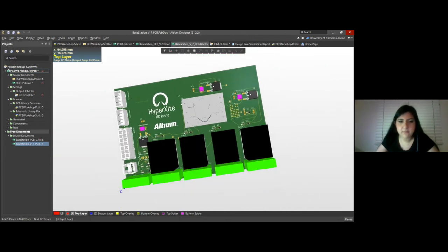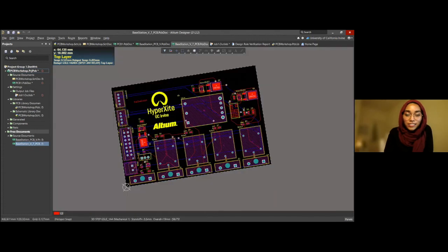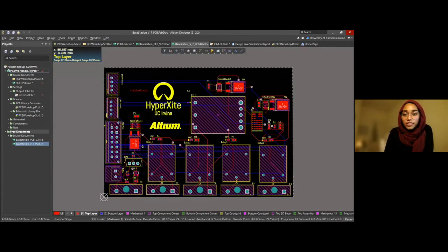But yeah, to answer Susie's question, why was it rejected? So for this design, we realized the smart diode, Beverly, correct me if I'm wrong, but the reason we didn't stick with the smart diode is because the smart diode doesn't have 100% duty cycle. So there's a period when the pod can turn off and the PCB wouldn't turn off in time, or the pod would turn off and then power would shut off to the pod. And so we realized we didn't want to use that because that's a risk. And so we completely got rid of the smart diode.